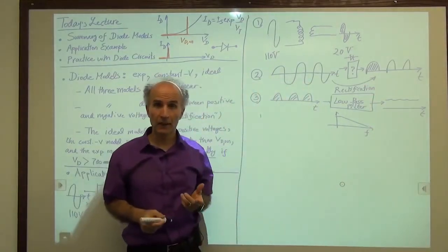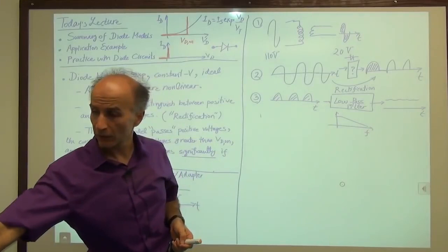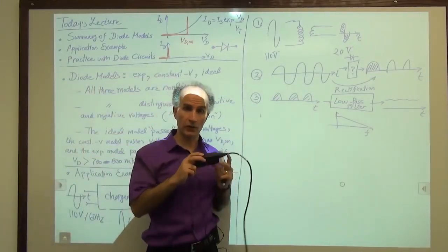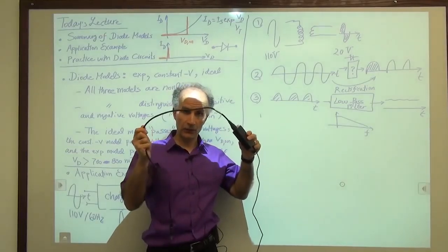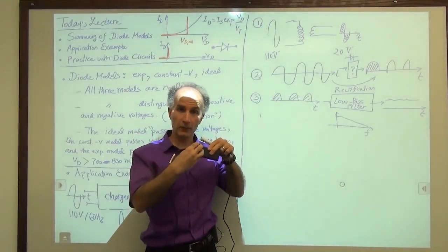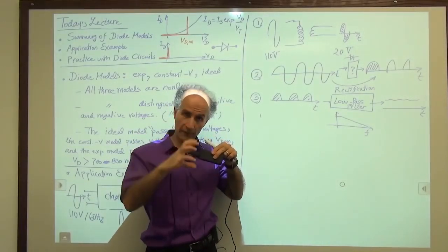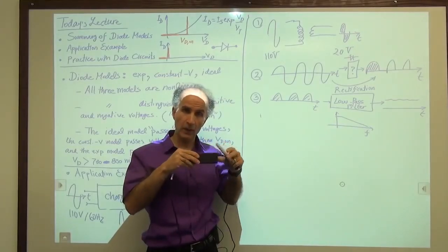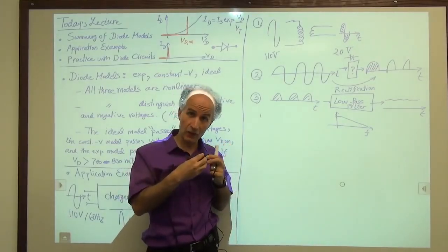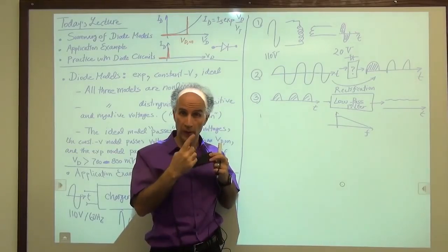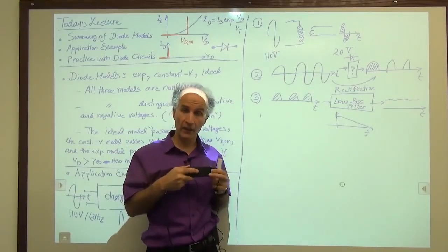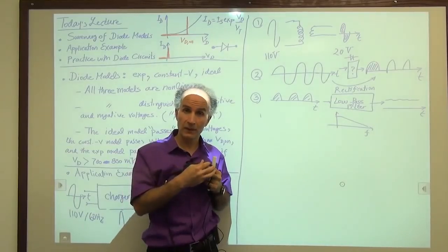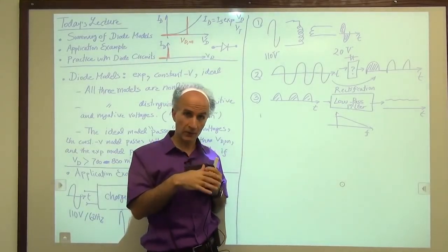So that's interesting. We see that this is what goes on inside this charger, right? So we start out with 110 volts or 220 volts. We have a transformer that steps it down, reduces the swing to something manageable. Then we have some sort of rectification circuit consisting of one diode or maybe more. As we will see, actually we might use 4. And then we go through some filter. A filter may consist of resistors and capacitors.